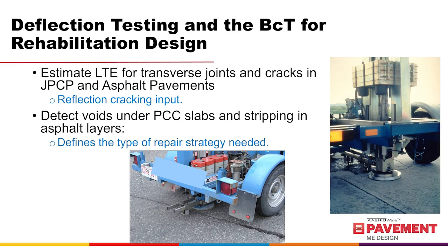Deflections are also used to estimate load transfer efficiency of joints and cracks in rigid pavements and transverse cracks in asphalt pavements. Load transfer efficiency is important to predict reflection cracks in asphalt overlays. Load transfer efficiency is a critical input to the PMED software. The BCT includes a feature to calculate the load transfer efficiency.